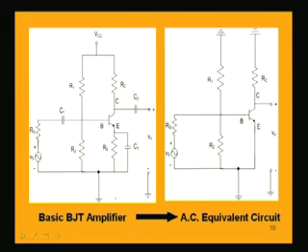So, following the steps, the first step is to make the DC sources 0. That is done by making VCC 0, or it is like short circuiting, which means it is grounded. So, the ground potential is 0, that is done. If we look at this point, it has two resistances, R1 and RC, both connected to VCC. Now, when we make this VCC grounded, these two resistances are also grounded. Just by showing this separately, we are conveniently showing that R1 is also grounded, RC is also grounded.